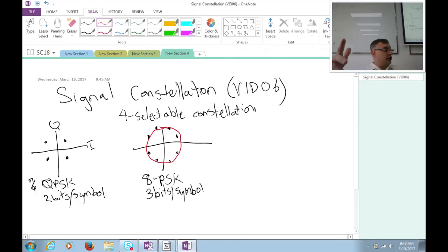We know in this class that that's actually good, right? Especially for a transmitter like a satellite that may have some nonlinearities. Why do they have nonlinearities? Well, at some point, your high-powered amplifier, you always want to operate near its nonlinear point because that makes it more energy efficient.